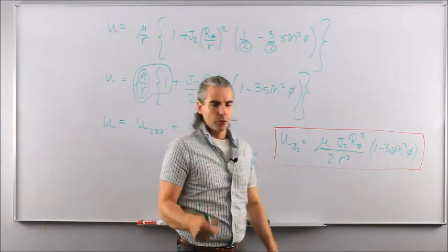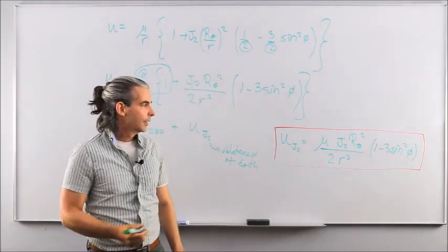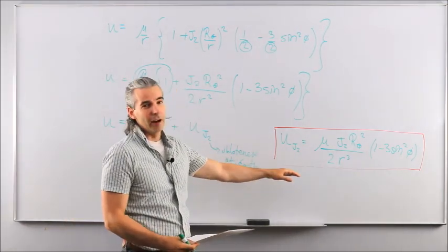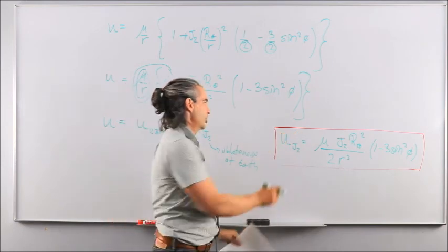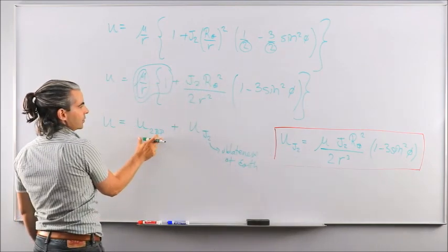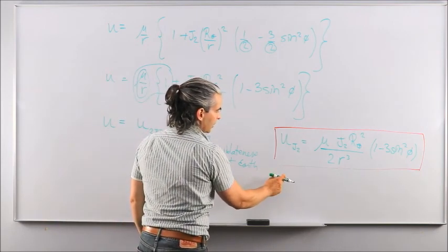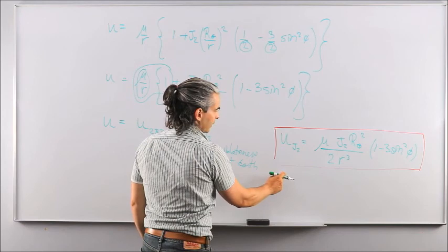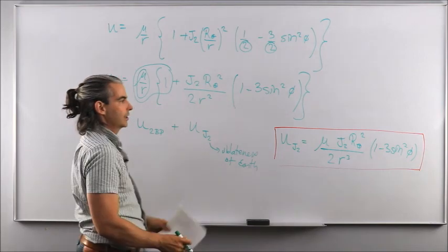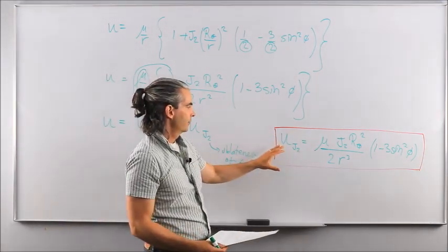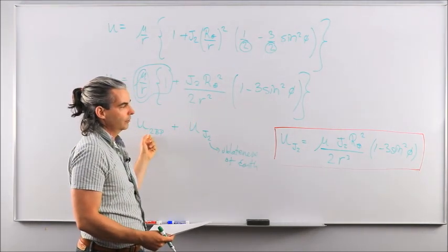In most research work or practical applications, we don't go up to degree order 20, but typically up to J5 maybe for the effects. So this is J2, the main contributor. Again, J2 compared to the two-body term is 3 orders of magnitude smaller, and J3, I believe, is 10 to the negative 5 in relative magnitude. So it's quite a bit more accurate to consider J2 than just the two-body potential function.